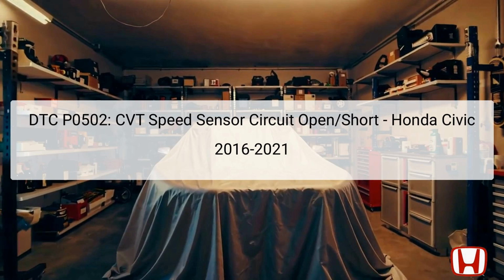The DTC P0502 pertains to a malfunction in the continuously variable transmission CVT speed sensor circuit, specifically indicating an open or short condition. The CVT speed sensor is located on the outside of the torque converter housing and plays a crucial role in detecting the number of revolutions of the secondary driven gear in the transmission.